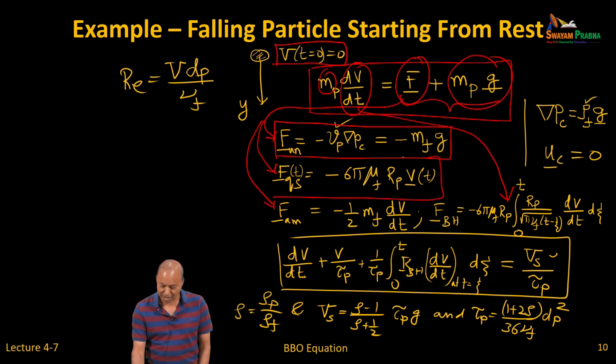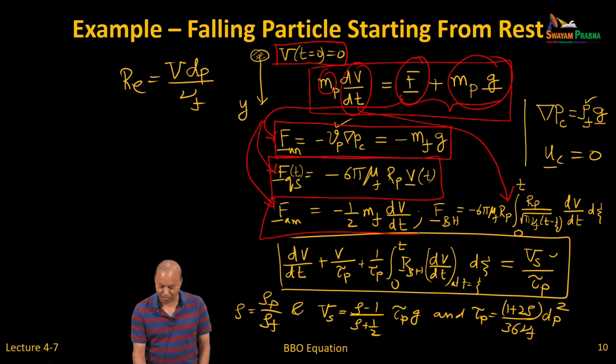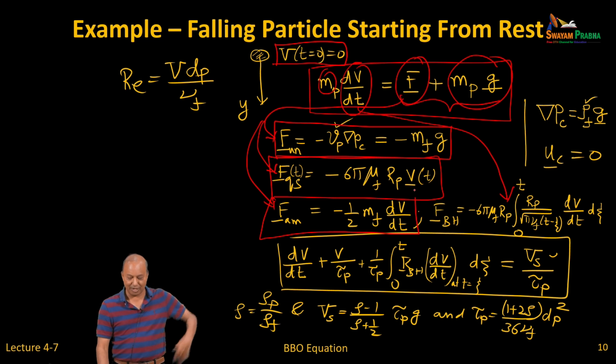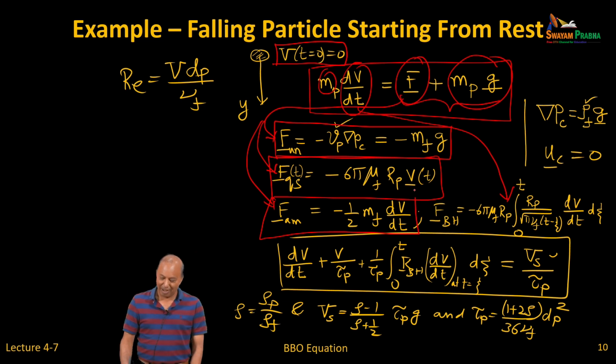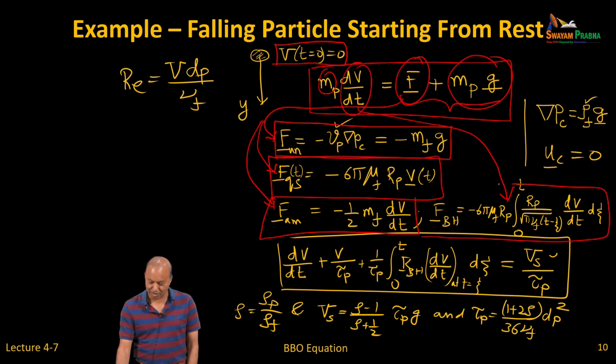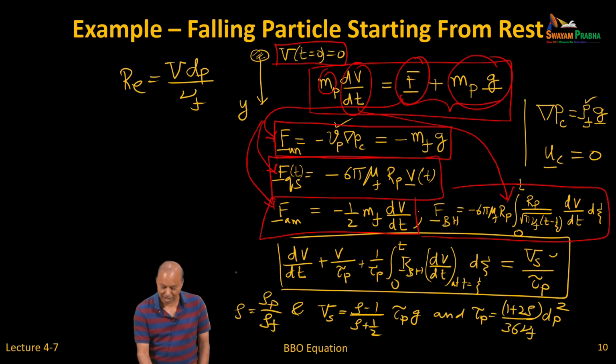For the quasi-steady force, the fluid is not moving, only the particle is moving at velocity v. So, you get this formula. Added mass force, similarly, the fluid is not accelerating, the undisturbed flow is just a stationary fluid. So, this formula is there. And Bassett history is the only complicated thing, then you can put that in there. And you do some simplification and you get this equation.